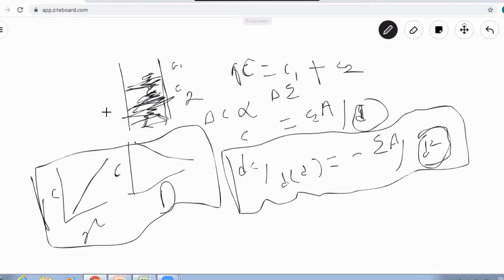Non-linear approach. When we provide the linear response, suppose we change the overlapping area or change the dielectric medium, so the capacitance will increase. That is proportional. But here it is inversely proportional, so that means it is a decrease. So there is a non-linear relationship.